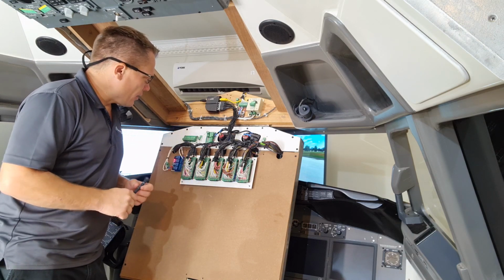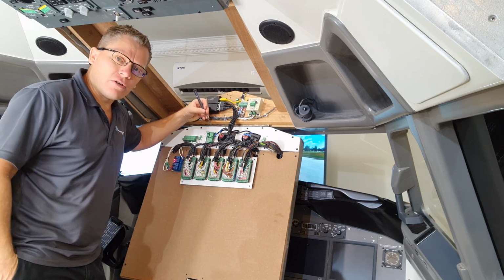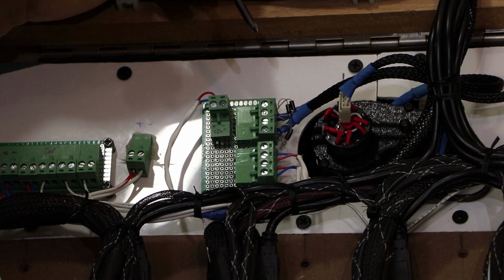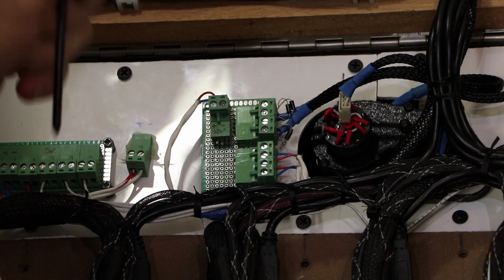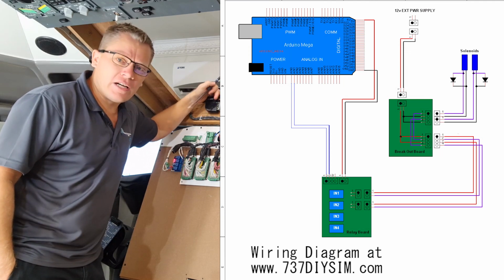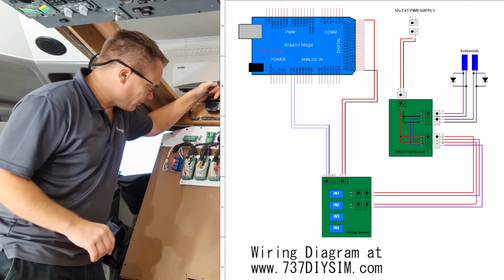And I do believe it was because I missed the diodes across the contactors of the solenoid valve. Once those diodes are in, and I just used some random ones that I had in an Arduino kit, everything works perfectly. So I can't stress the importance of using the diodes across the solenoid valve to remove the back EMF once you release the solenoid.